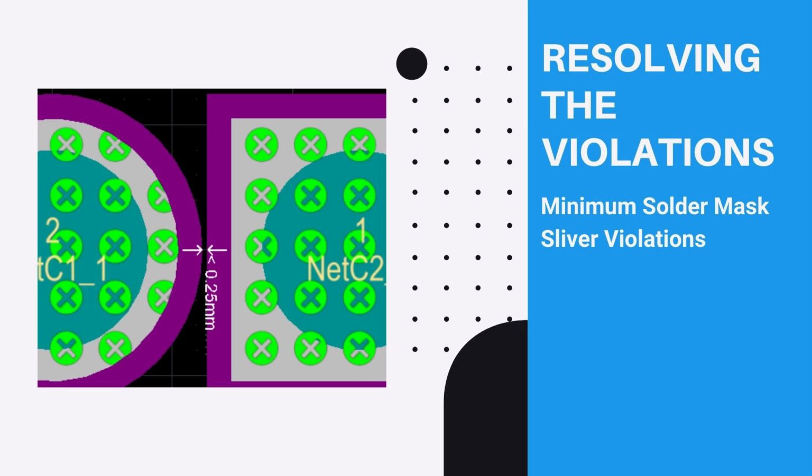Note that the solder mask layer is defined in the negative. The objects you see become holes in the actual solder mask. During fabrication, solder mask is applied using different techniques. The lower cost approach is to silk screen it into the board surface through a mask.